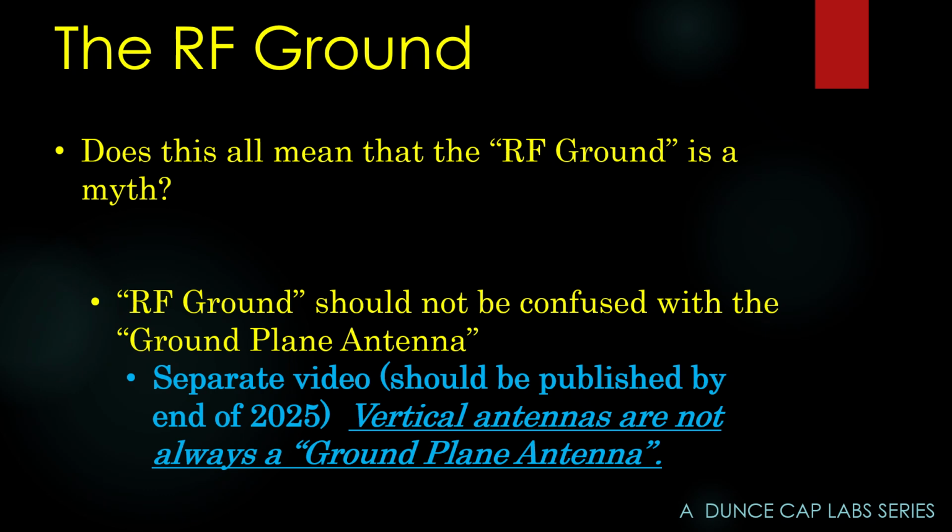Now, before I move on, there's one thing I've got to mention. RF ground should not be confused with the concept of the ground plane antenna. I'm going to do a separate video on just the ground plane antenna, hopefully by the end of the year of 2025. Just keep in mind, not all vertical antennas are a ground plane antenna. And again, I will come back to that later.